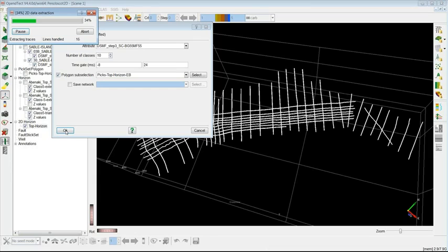when it wants to apply the result, to segment and match, a window will pop up asking the user to select the 3D horizon. If there is no available 3D horizon, the same window allows the user to create a 3D horizon by using different types of gridding algorithm. We have triangulation, extension, and inverse algorithm, you name it.